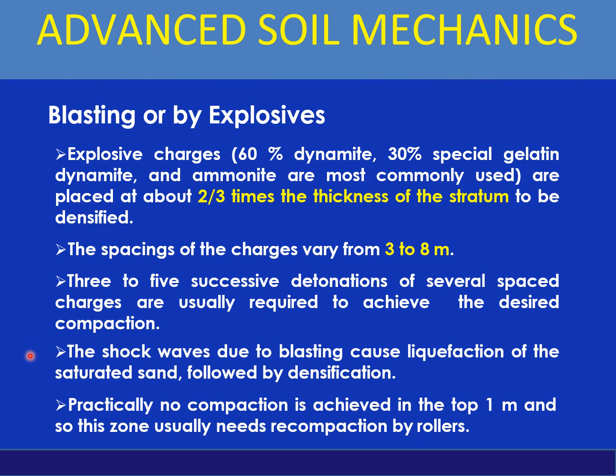The shock waves due to blasting cause liquefaction of the saturated sand followed by densification. Practically no compaction is achieved in the top 1 meter, and so this zone usually needs recompaction by rollers or by using conventional techniques.